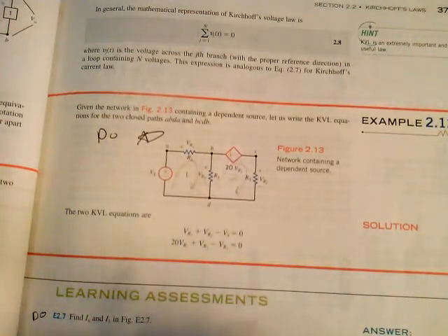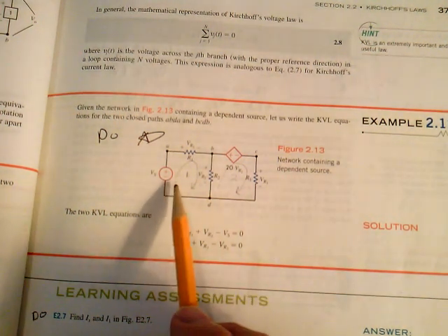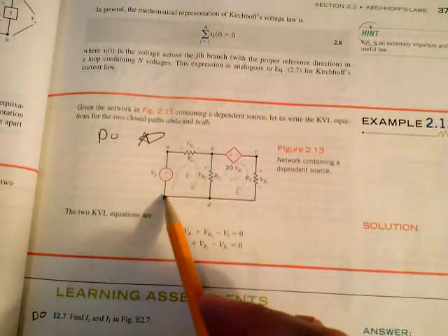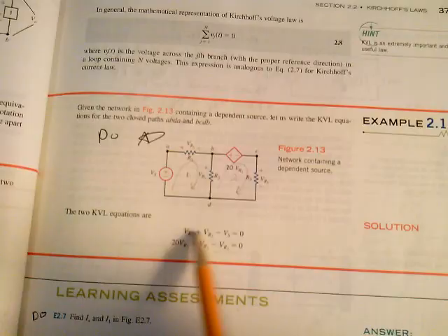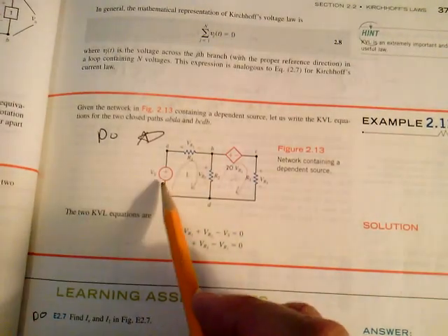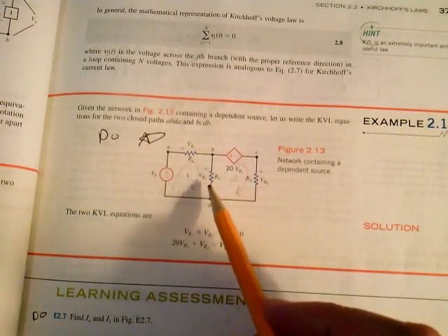These aren't nodes now, we're doing loops when you do voltage law. So the Kirchhoff's voltage law, you're going to say around loop 1 by Kirchhoff's voltage law. And you start down here and you write the voltages around. And you're going to get this equation, or the negative of that equation. You're going to get a plus Vs, a minus VR1, and a minus VR2 equals 0.